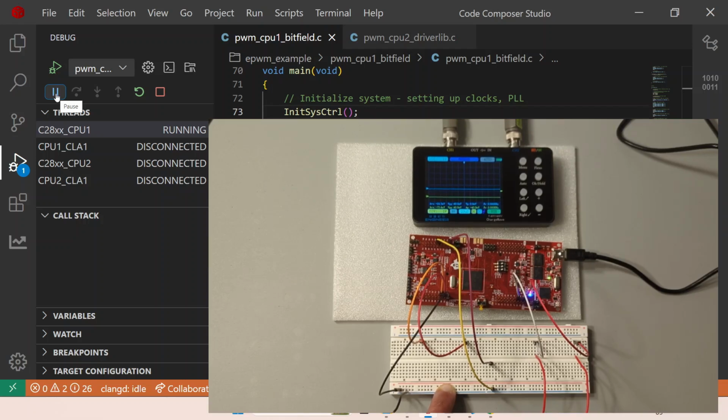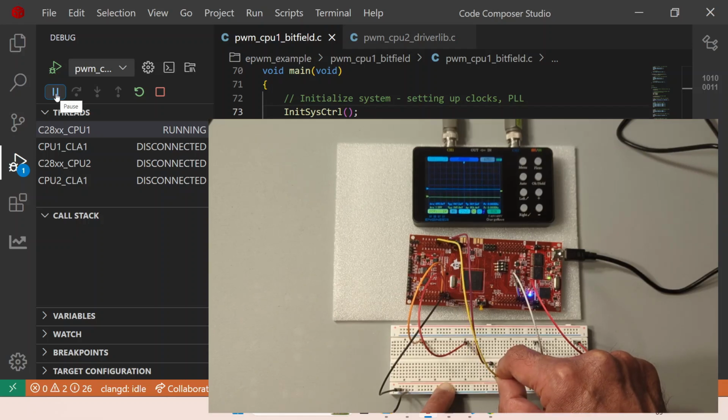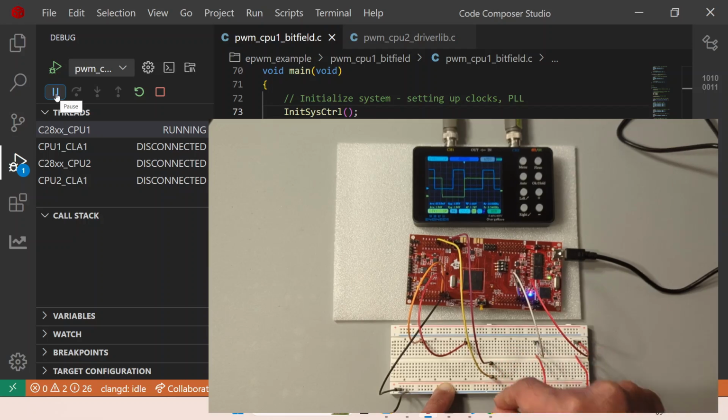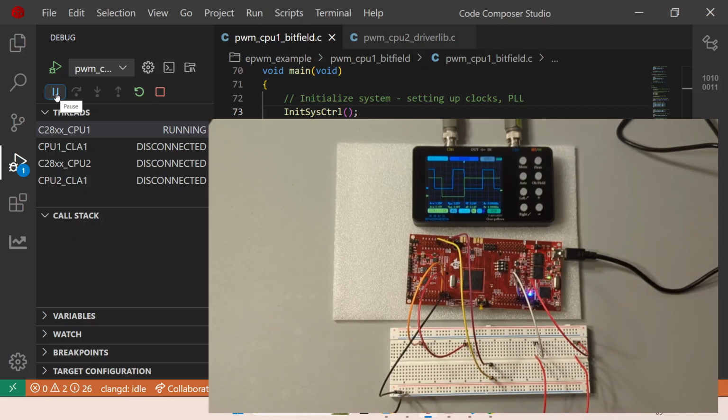For example, if I were actually connecting GPIO 97 to the fault output of my power module, and the power module was giving an overcurrent fault, then this would block all the gate waveforms. To revert, I'm just going to take it out, and you'll see again that fluctuating waveform, and if I connect it to VCC, you will see that the waveforms are back and they are steady.